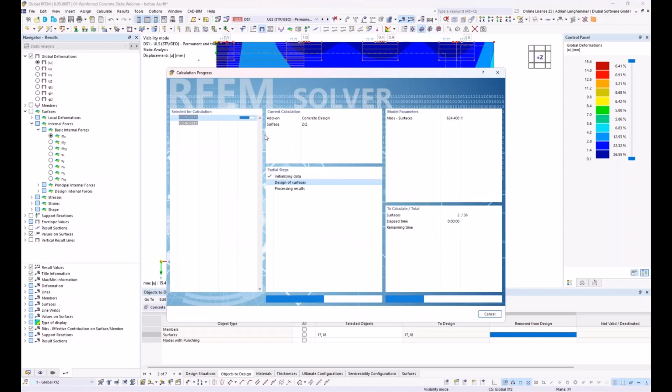I could calculate again, and now I see that there's changed a little bit for the calculation. I have now two concrete entries. The first calculation is the required reinforcement. So with changing the reinforcement, there could be also changes regarding the inner ladder or the effective depth, depending on the defined reinforcement. And the second calculation is the automatic design of the existing reinforcement.